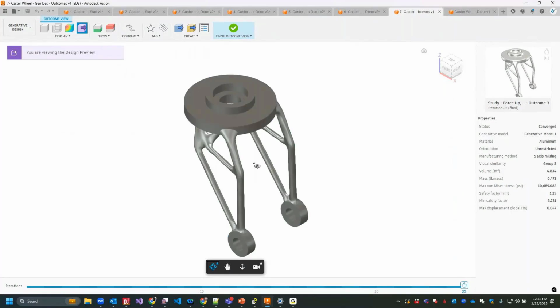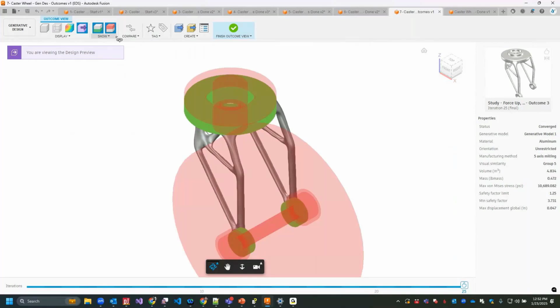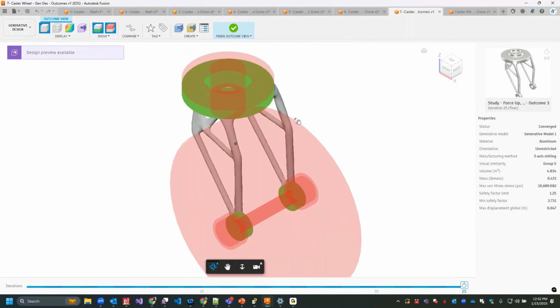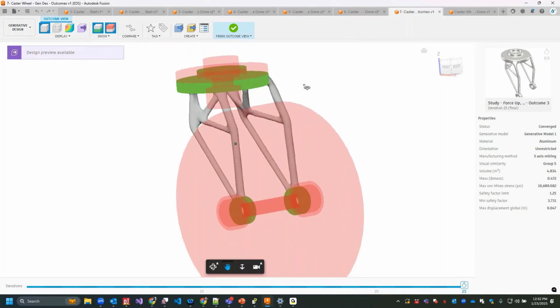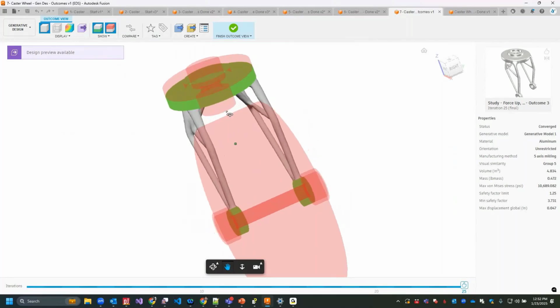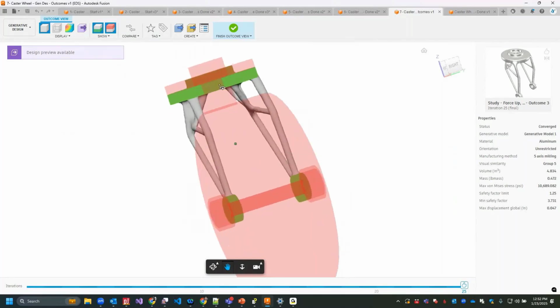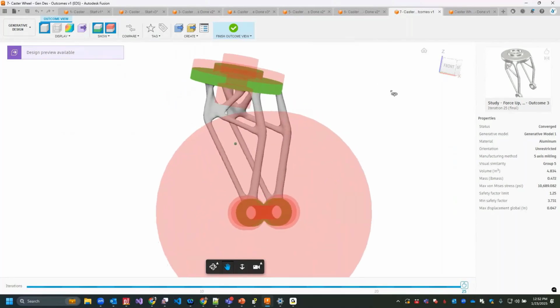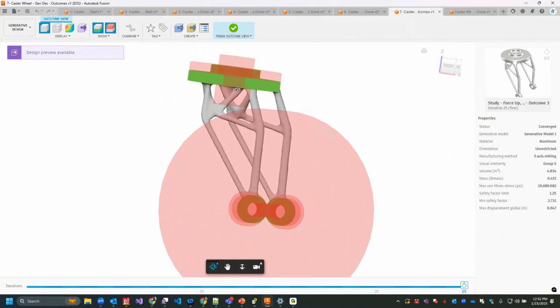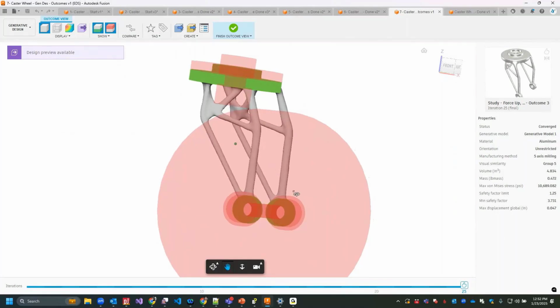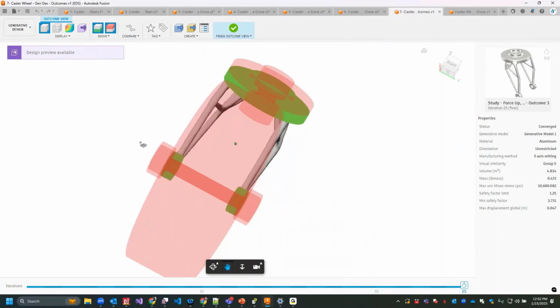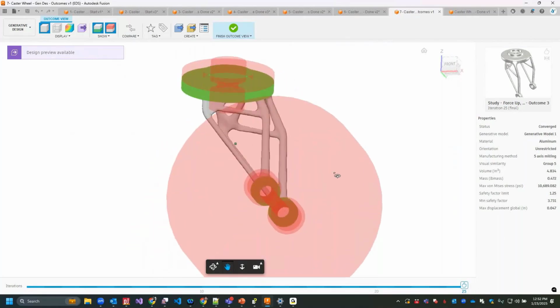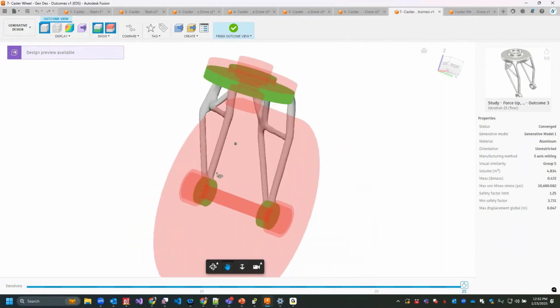There's design previews of what it's going to look like when you export designs. You can actually see the preserved geometry and also the obstacle geometry. So if we take a look at this, you click on the model view and then rotate this around here, you can see that it has not grown into anything that we set as obstacles. It's taken the preserved geometry and grown from that preserved geometry down to the other geometry we have, but it has not grown and created any structure inside of the obstacles that we have.